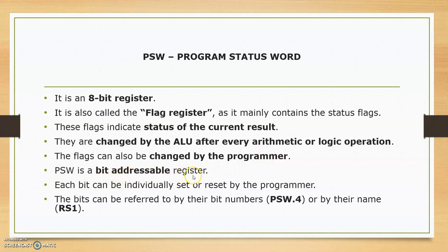PSW is a bit addressable register. Bit addressable register means the individual bits can be set or reset by the programmer. There is no need of changing the whole byte to change one bit of the register. We can access each bit individually.